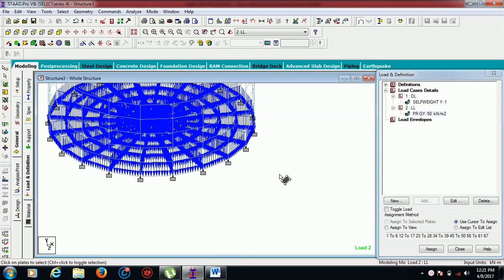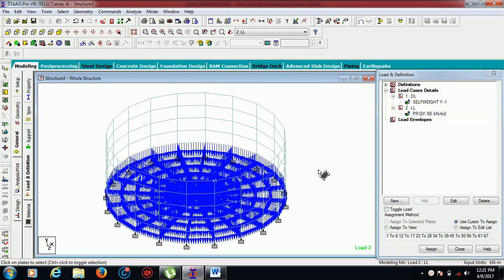But as I described in my water tank design of rectangular water tank, whenever there is a fluid or a hydrostatic anything, water or any liquid kind of thing, it tends to exert pressure on the side walls also, and the magnitude of this pressure or load tends to increase at the bottom as maximum, and at the top it is minimum because of the hydrostatic nature. So for that we have to create one more thing, and this is the most important and technical thing.